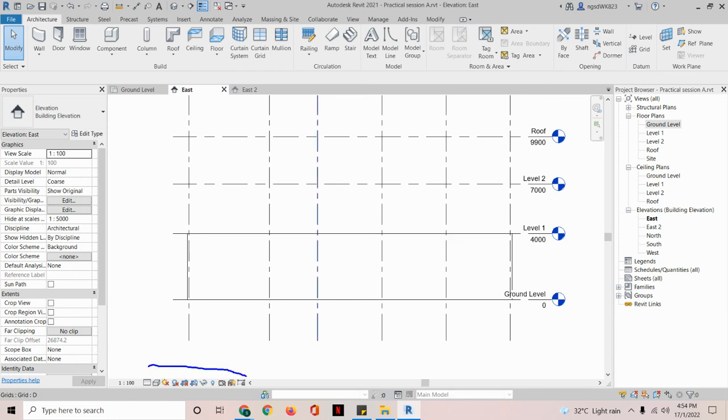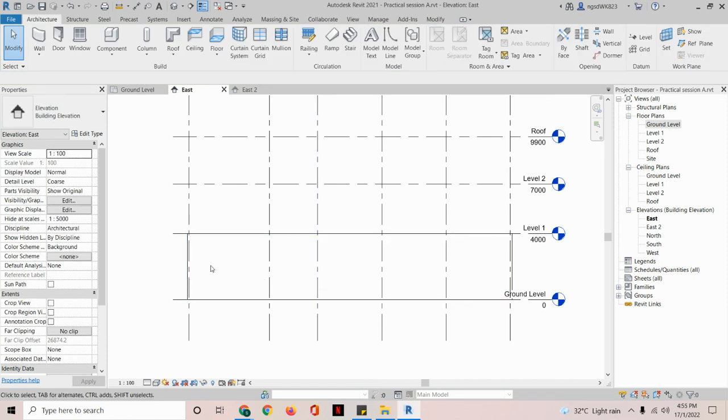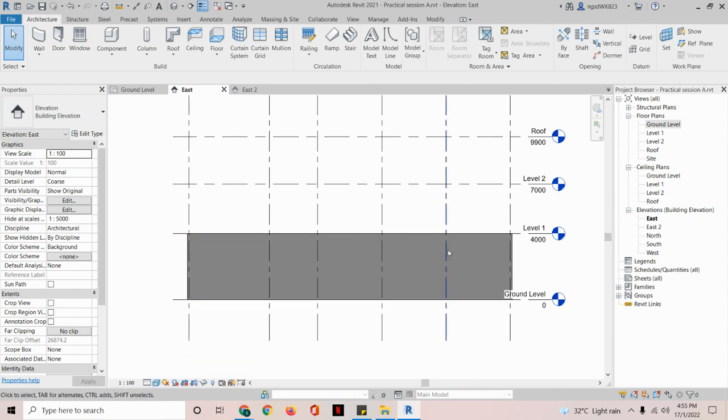So this is where we have the function down here. So the function down here, by right, this one we just remain it as cost. We don't really need to care much about this. What we want to show is the visual. We want to look at the visual. Is the wall created properly? So we created a wall that's constrained towards 4 meter. If we hover our mouse over this wall, we know that this wall is here, but it's not clear. So what we do, we click on this visual style, and then we can click on shaded. Then we are able to see our wall.